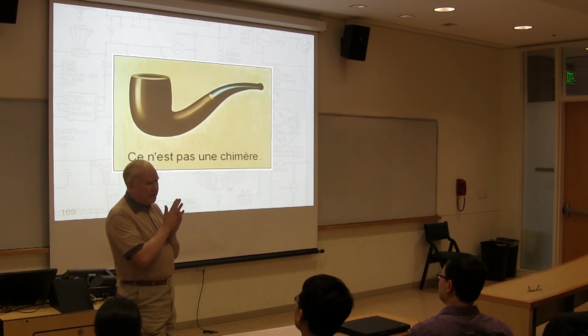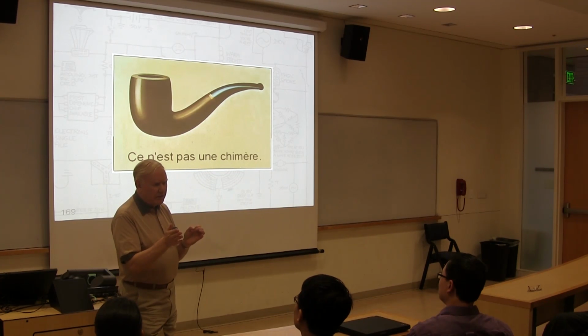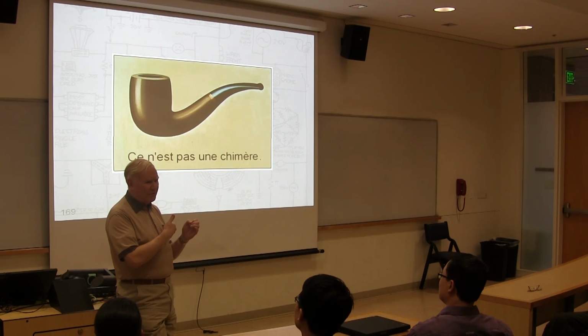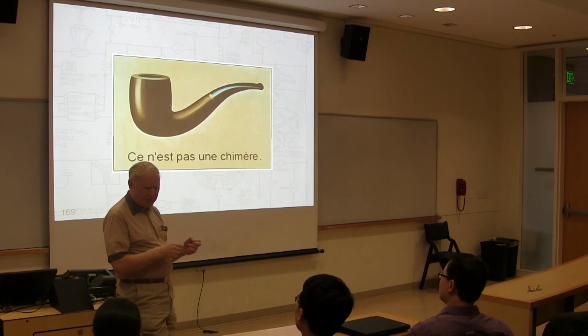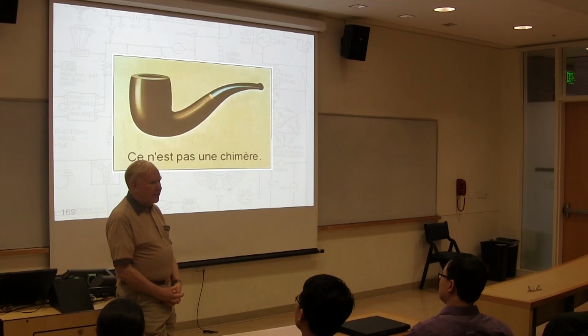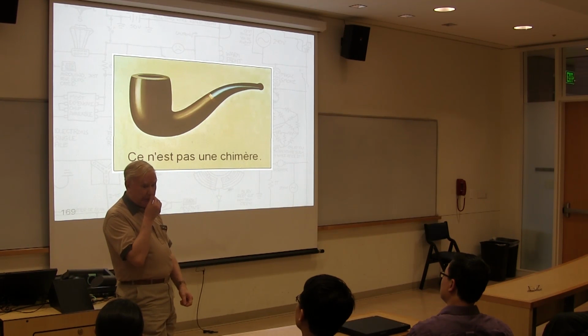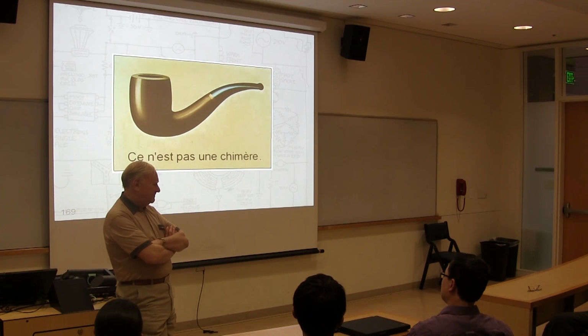But you're quite right. And of course, the other thing to mention, I think you're talking about maybe a 65 nanometer kind of node, and that's very expensive if you want to run products on a whole wafer. You're lucky to get a little bit of the wafer, a square centimeter, whatever. But the mask costs are getting on for $1 million just to make the masks, and the wafers themselves are very expensive. So you have to be dead sure that this product is going to sell by the millions, because you can make millions on a 300 millimeter wafer. So it's a dilemma. But you're quite right. I think in the end, digital's going to win out, but we'll see. Thanks.